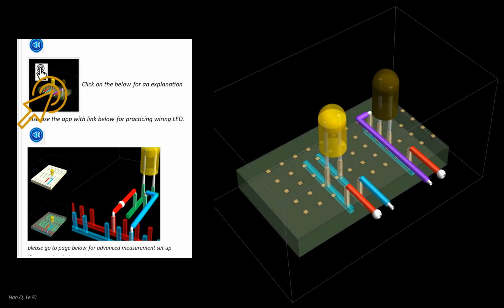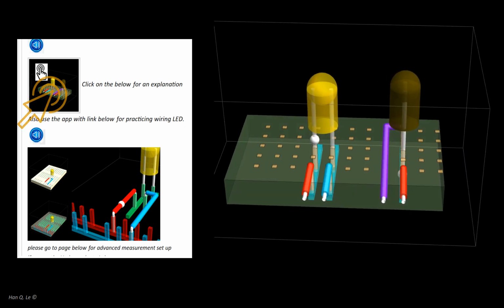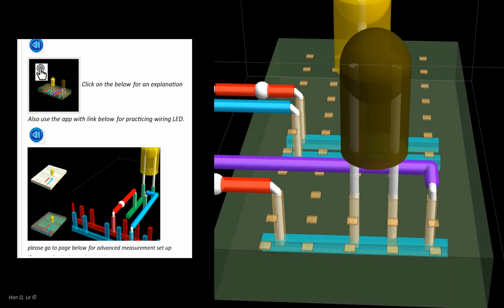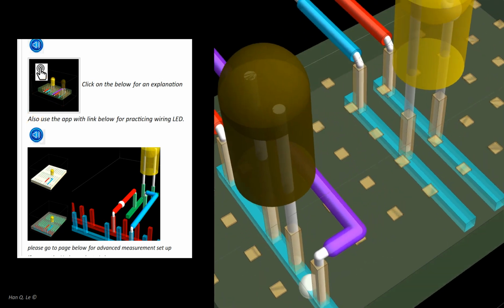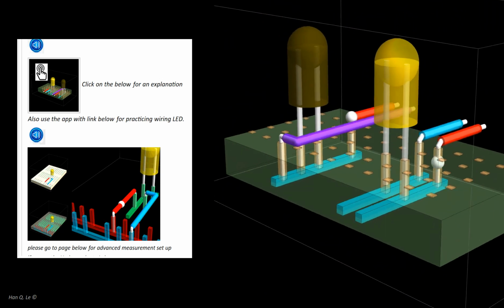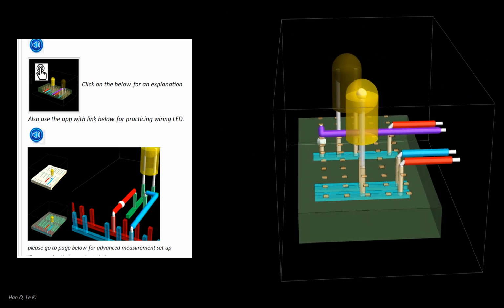For the first-time breadboard and LED user, if the previous mental exercise on LED wiring configurations is not obvious, this additional applet can give a 3D perspective of a correctly wired LED that lights up, versus an incorrectly positioned LED that will not light up. The dark LED is inactive because the current bypasses underneath its terminals, rather than going through the device.